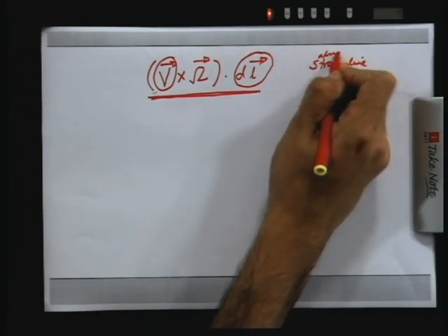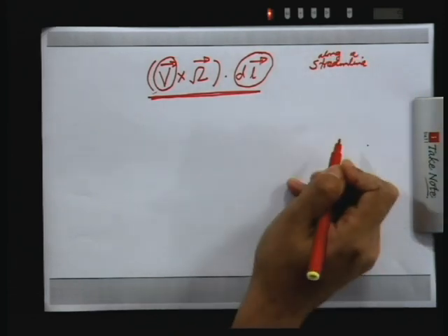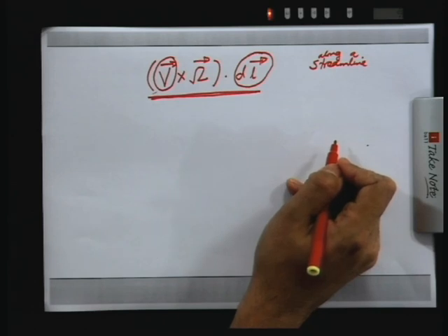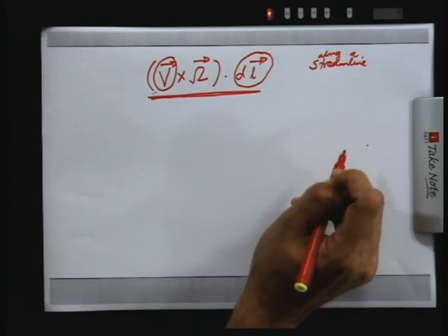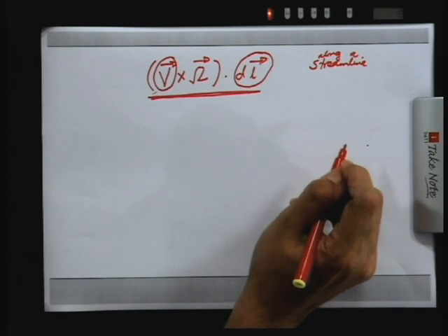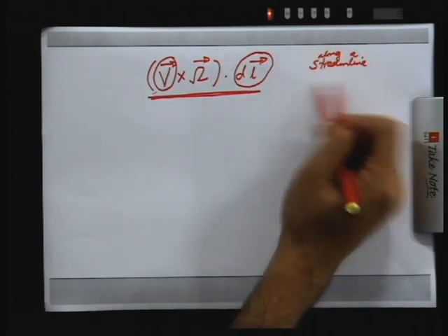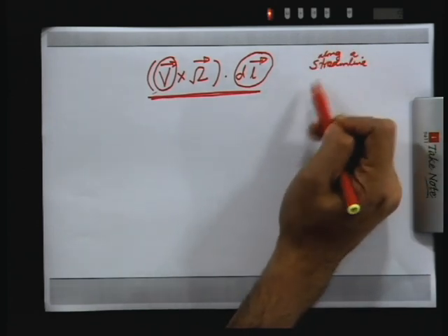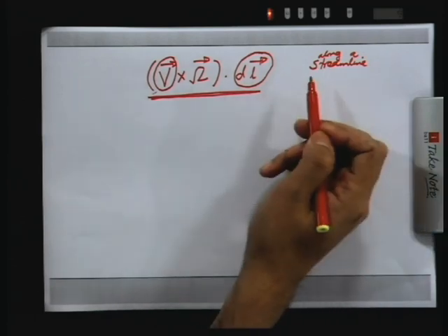In the siphon, if you consider a streamline, you can apply the Bernoulli's equation between 2 points, provided you model the flow as inviscid, constant density flow, or the flow of an incompressible fluid, and steady flow, and along a streamline. Otherwise there are several other conditions in which you can apply.